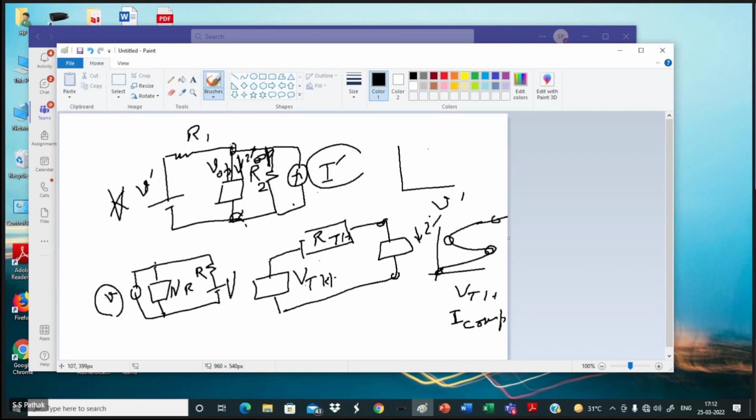What is going to be the small value v, so that this becomes that particular coordinate system's point. And accordingly the current is known. So when this current is known, how much current is coming through this and through this, you have to use Thevenin's equivalent circuit for that, and you can define how much current will be coming through that. You will be able to plot with shifting in the coordinate point in that previous curve.